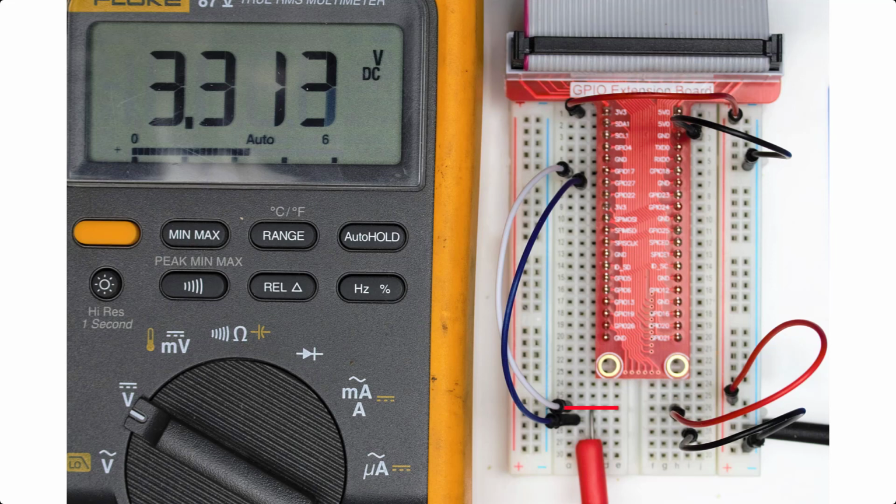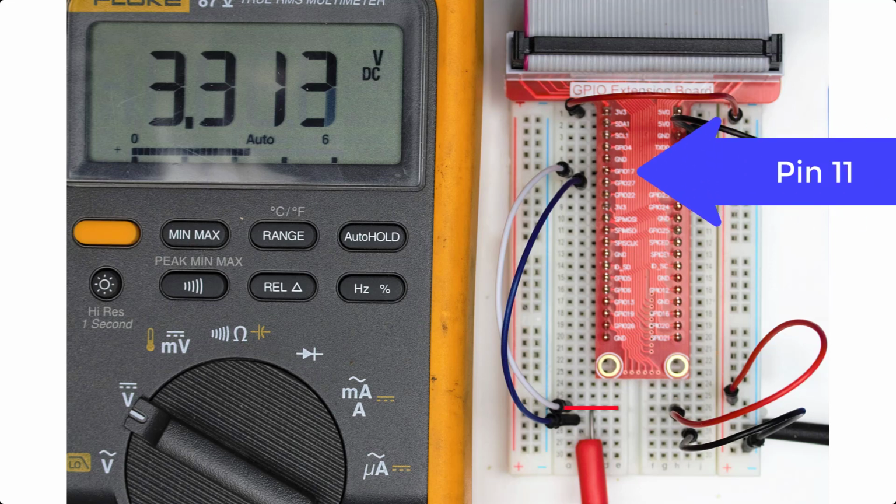Hopefully you recall that a breadboard is used in order to do some experimentation on electrical components. The way that a breadboard works is the rows, which are identified by the numbers on the left or right of the row, are all connected together. So every point along pin number 26 or row number 26 is electrically connected. So now that I have my red meter lead here on row 26 and my white jumper wire on row 26, those are essentially touching each other. And so we simply moved down the jumper wire just to make it a little easier for measuring.